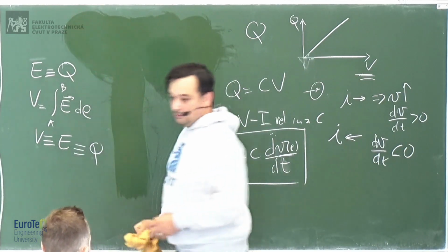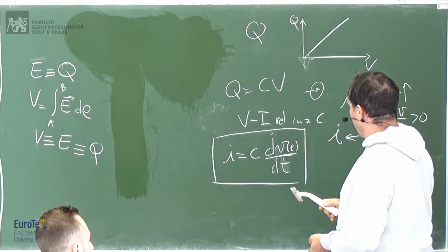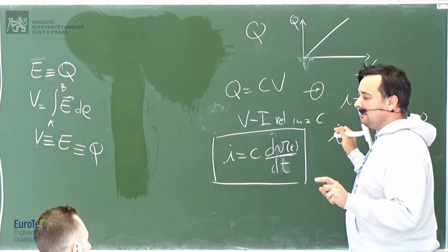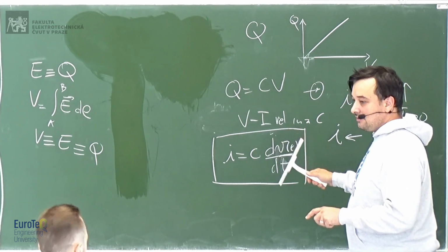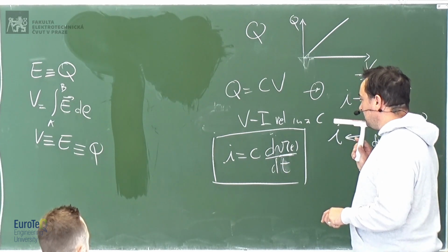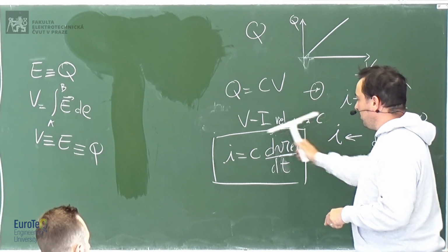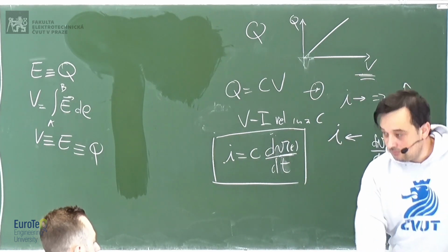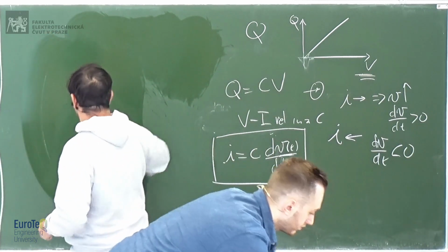And what about the C in that equation? The C would affect the slope of that derivative, wouldn't it? Well, let's really go step by step. It's maybe better because then we will see the effect of the C in the transient. One thing which is interesting is the energy that the capacitor stores. But before getting to that, let's see what happens to this equation when we go to sine waves, because that is most commonly what happens in an electric system.